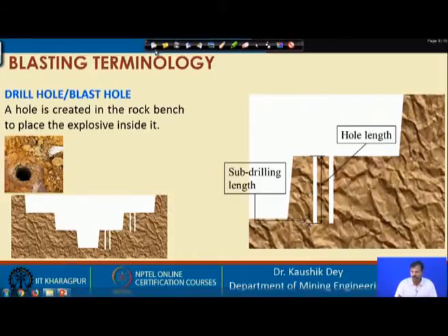Instead, if we drill only up to this level, our fragmentation will become like this, and a portion of rock will remain at this position, forming a ridge. This portion of rock mass will remain there after the blasting. To avoid this, we go for some additional length of drilling.